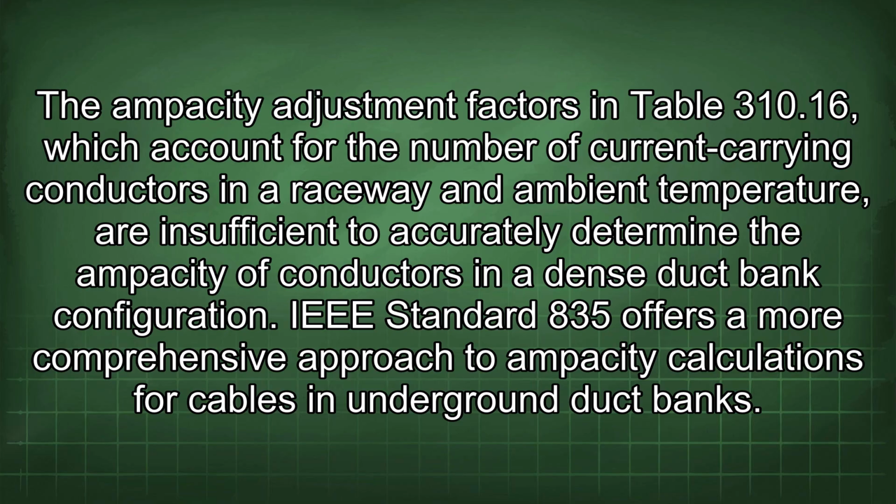The ampacity adjustment factors in Table 310.16, which account for the number of current-carrying conductors in a raceway at ambient temperature, are insufficient to accurately determine the ampacity of conductors in a dense duct bank configuration.